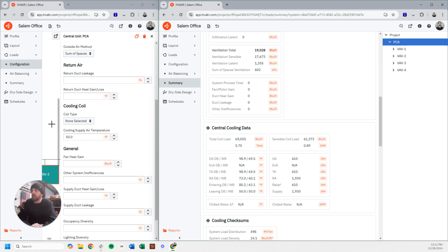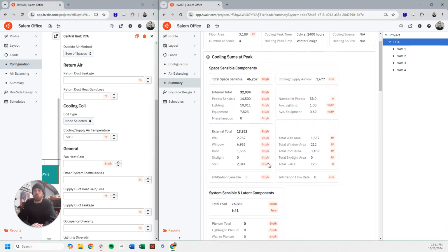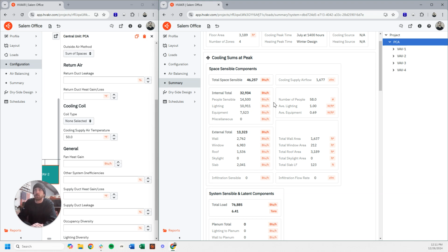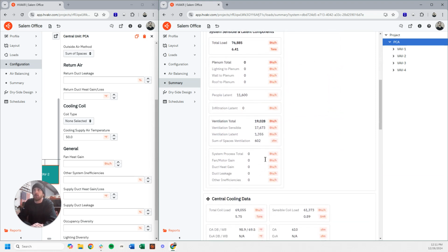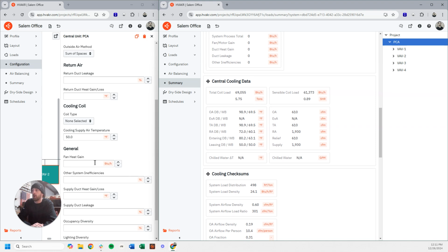So this right here is one thing to pay attention to when you are configuring your system and looking at how your coil data matches with your raw, kind of agnostic load calculation here. So that's just a quick primer on looking at your discharge air temperatures, looking at how that affects the psychrometrics, and ultimately how that affects your total and sensible and latent loads for your coil.